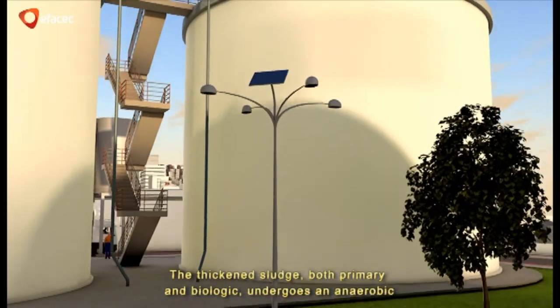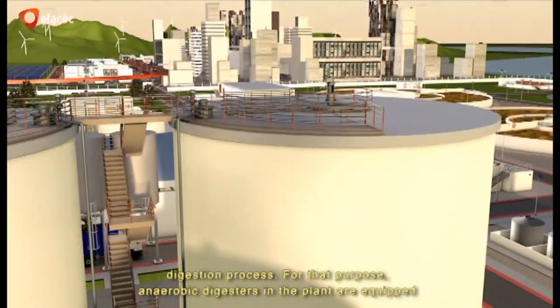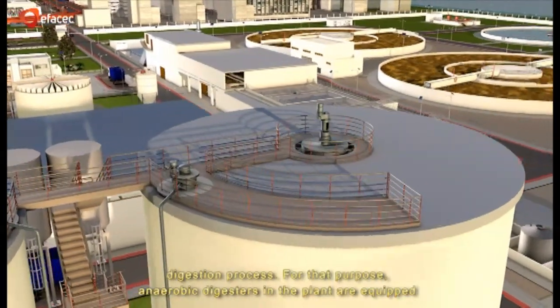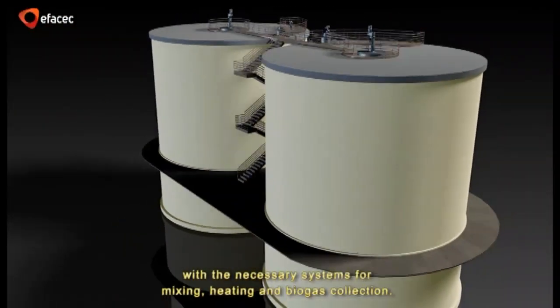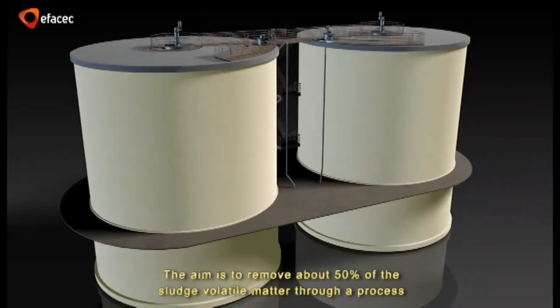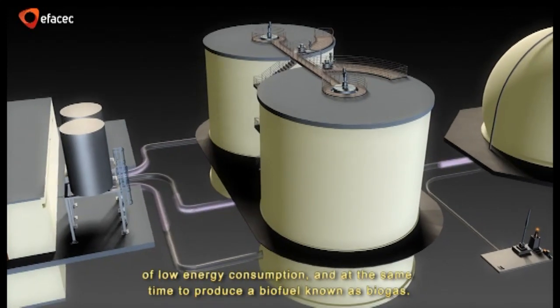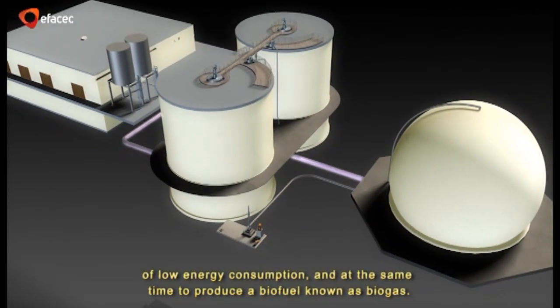The thickened sludge, both primary and biological, undergoes an anaerobic digestion process. For that purpose, anaerobic digesters in the plant are equipped with the necessary systems for mixing, heating, and biogas collection. The aim is to remove about 50% of the sludge's volatile matter through a process of low energy consumption, and at the same time to produce a biofuel known as biogas.